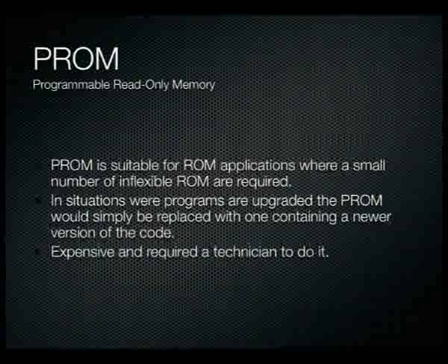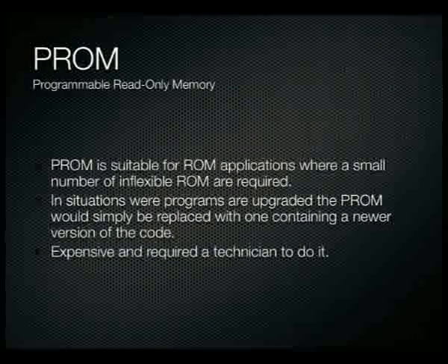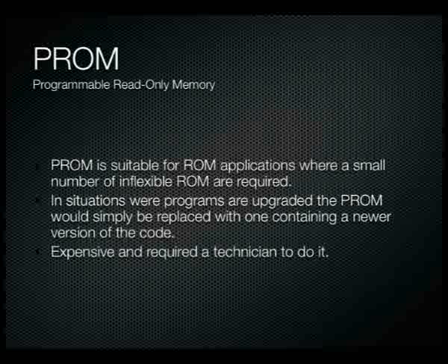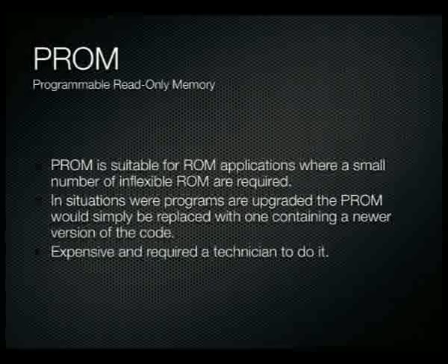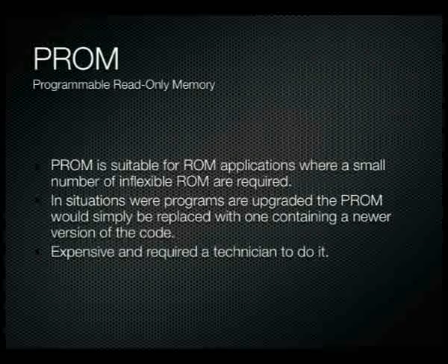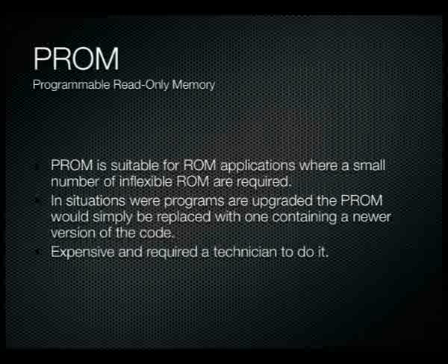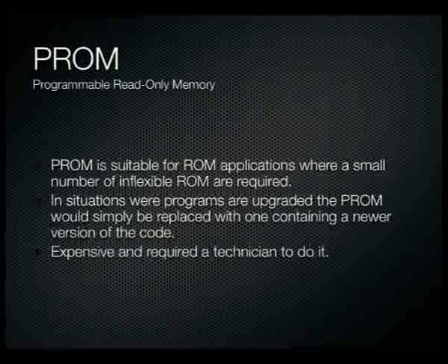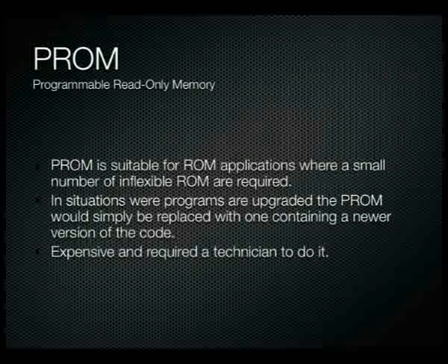So PROM is suitable for ROM applications where a small number of inflexible ROMs are required. Because you're burning them yourself, you don't have to have a large quantity to be able to get the cost down. You simply buy a single PROM chip, burn it up, and you can use it in your application. So the cost is already quite low.